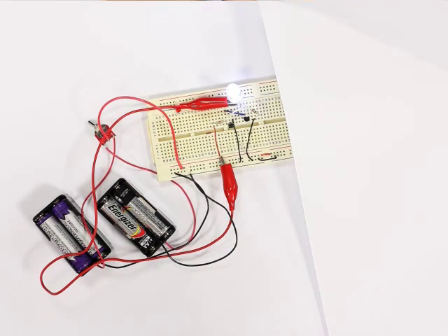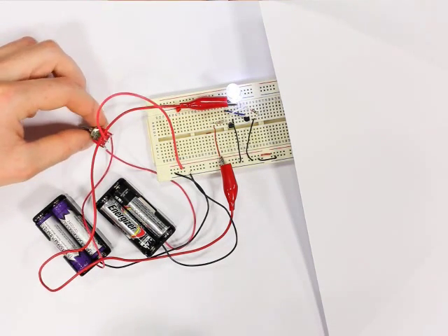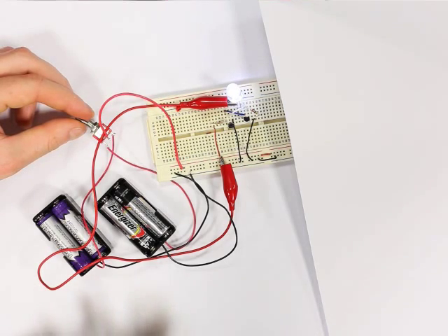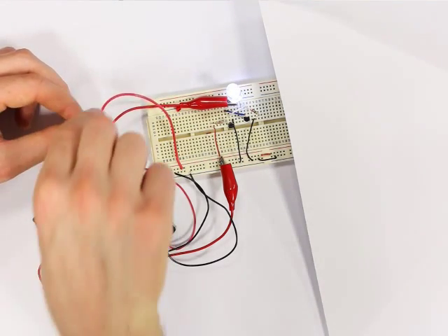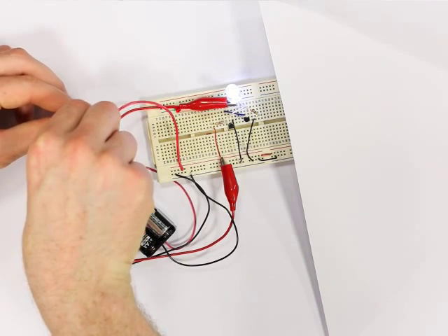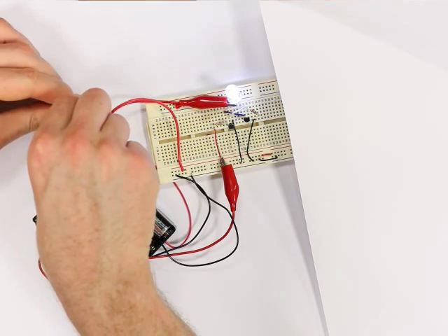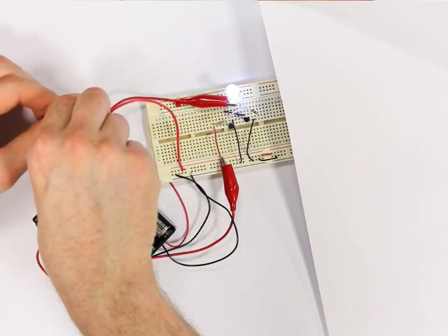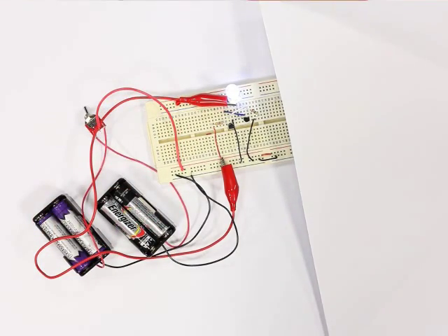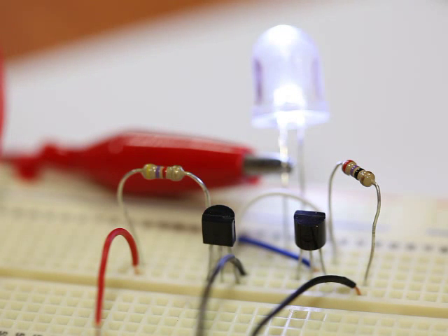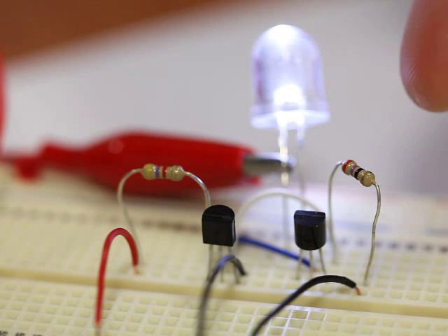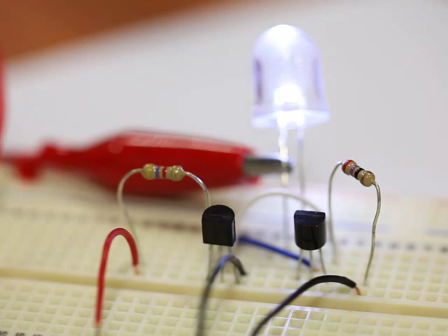There we go. That looks pretty good. And once again, I can switch between power supplies. I'm currently on the rechargeables. And there's the alkaline. And you can see there's really no perceivable variation in brightness between the two. So that's pretty good. Our constant current circuit is clearly working. So just in case you couldn't make out the circuit from above, here's a different view. We have sense resistor, MOSFET, BJT and gate resistor.